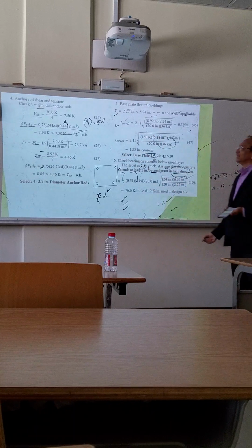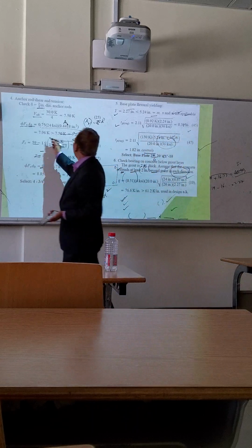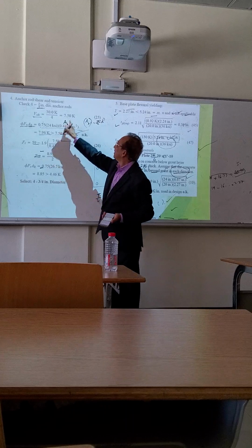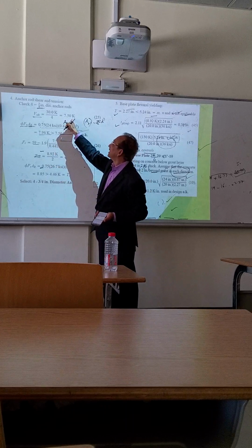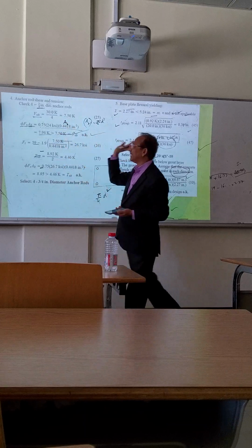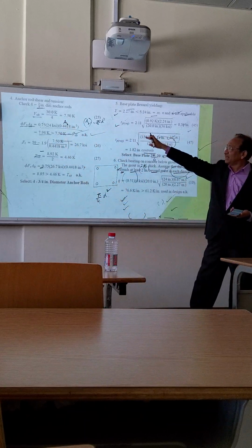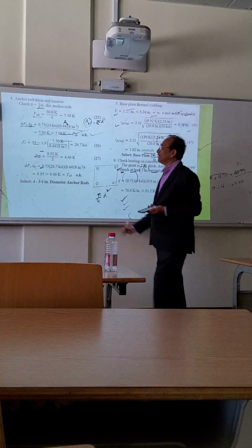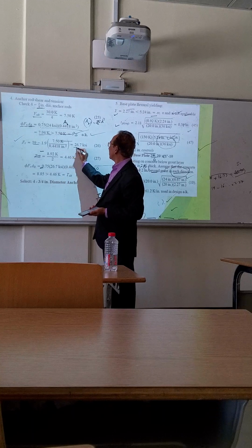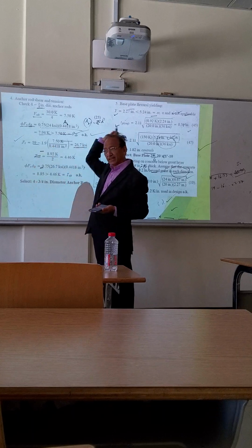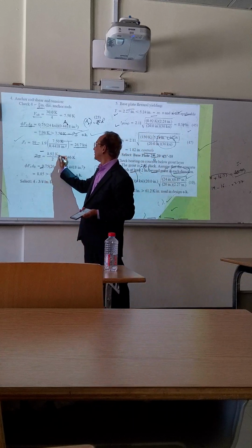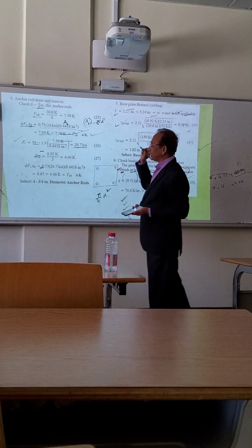Okay. So in that case now, we find this, and this value comes out to be 7.96, which is more than the force coming on the bolt. So it is safe. So we check that the bolt which we have designed is safe in shear. Then we come to tension. For tension, we calculate this value, which is 26.7, by using that formula for our bolt. So Tub is 8.92, that force which we calculated.